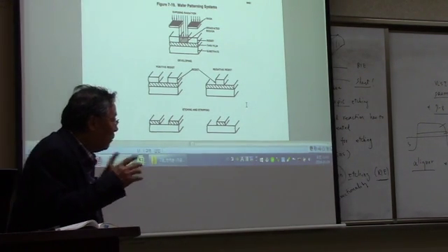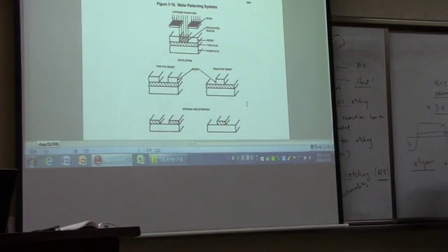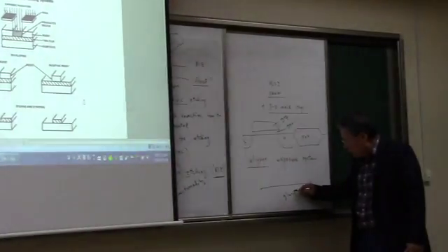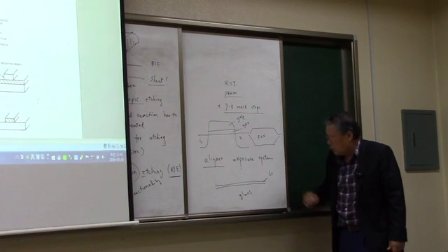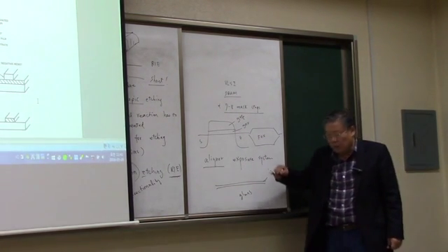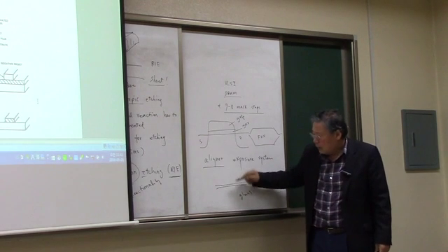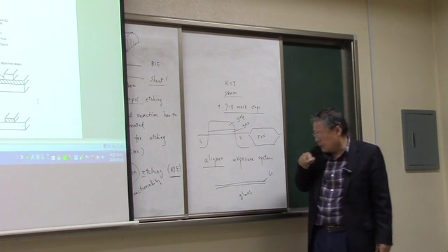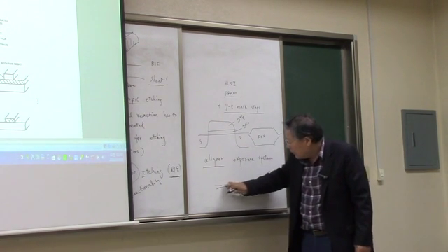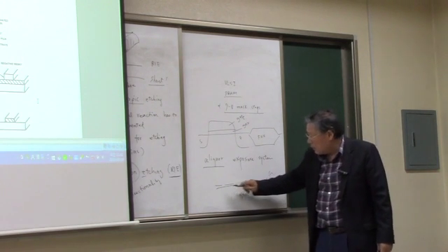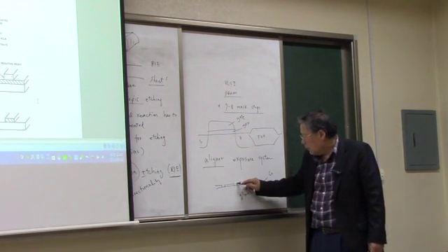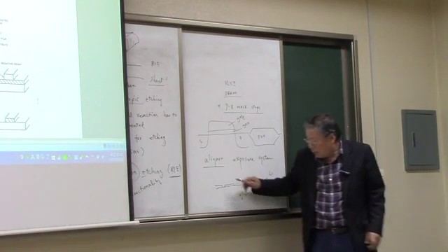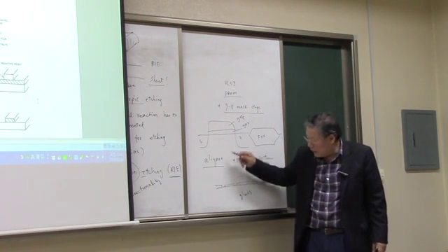And the mask is going to be prepared on the glass. And then we usually use chrome metals, okay? And then with the laser, you create a pattern. The pattern means you just make the part of the chromium layer where the light can pass or light cannot pass.